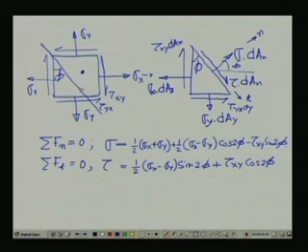So that clockwise moment is positive, and this is taken in the negative direction. So we have a negative stress, and this is also a negative stress because it is creating a counterclockwise moment. Under these notations, we give the force equilibrium equations like this.